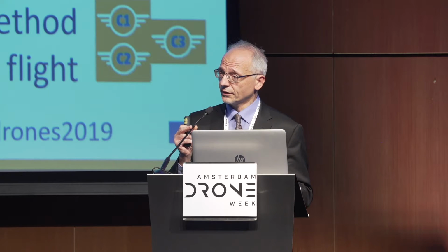The 19 meters per second comes from the reasoning which led to the establishment of the 900 grams for class 1, in consideration of a drone of 900 grams that falls with a terminal speed. And therefore, if you make some calculation, which you also find in some accompanying document to the regulation, you come up to 19 meters per second as a limit on the maximum speed in order to preserve this kind of energy and maximum weight.